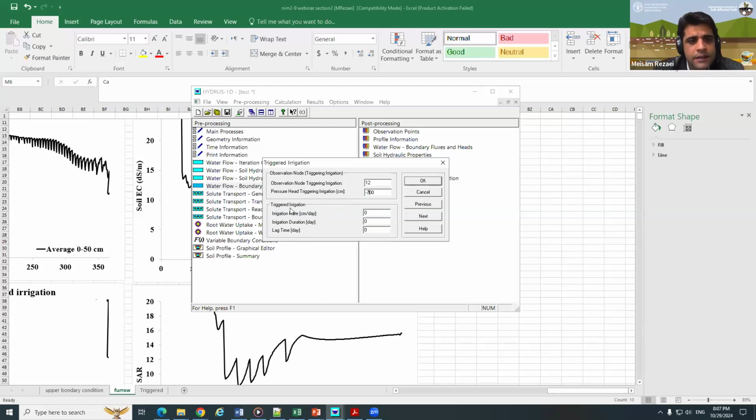So for the tree-grade irrigation, for the irrigation rate, as an example, I say every 2 or 3 days, I want to have 2 centimeters of water, with a lag time, which means every 3 days, or I would say every 8 days, because I don't have tape or drip irrigation. I want to again use furrow irrigation, but with optimized irrigation scheduling. So the irrigation duration would be like 4 hours per hectare, or even less, for 2 centimeters or 10 centimeters. It's just an example.